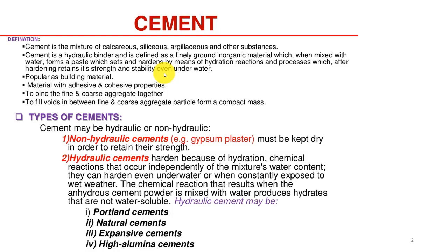So by using sand or any other type of filler, you have occupied your coarse, macro-sized voids. What about the micro-sized voids that are created among the fine aggregate particles? These voids can be filled by the binders that you are using.